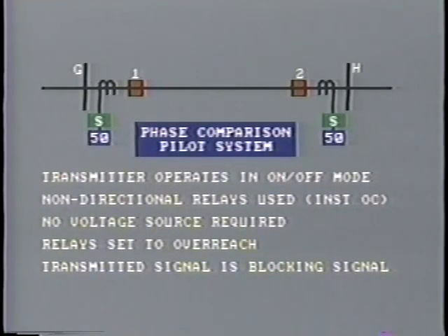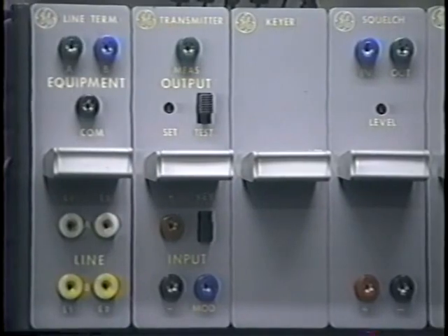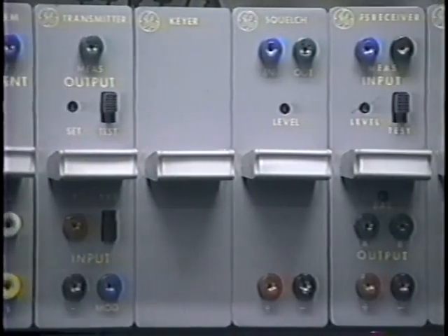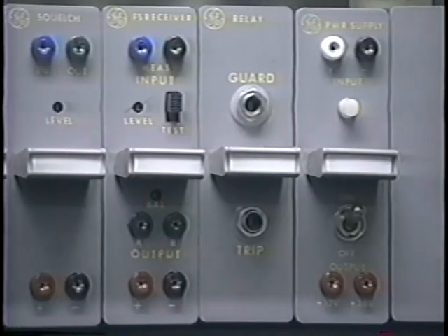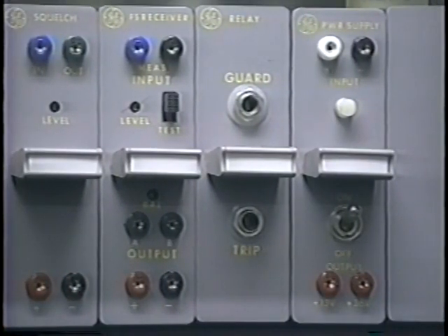If the communication channel fails, the protection system will still operate, but it will trip incorrectly for external close-in faults. In all of these pilot protection schemes, the logic circuit is quite complicated. Solid-state circuits are frequently employed, although complete electromechanical installations are still widely used.